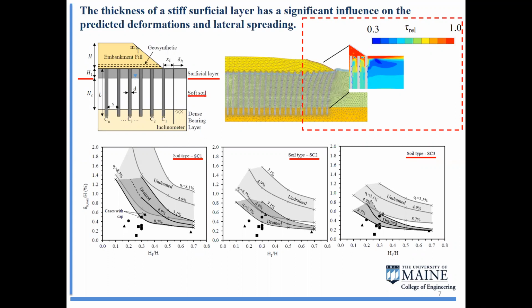Now, if the stiffer surficial layer yields and offers no further confinement at shallow depths, significant column rotation and separation in the trailing columns could lead to an appreciable redistribution of stress in the foundation soils at basal instability. And a practical design objective would be to achieve area replacement ratios that achieve an acceptable amount of mobilized shear strength and lateral spreading, okay, which does not necessarily preclude column yielding or fracturing based on our numerical analysis.